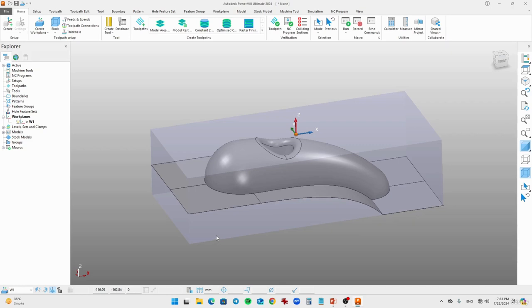In this model area clearance, we are going to apply the roughing operations, all the roughing operations, to give a certain shape to the block. In such operations, you will get a rough idea of how your workpiece looks. For this operation, you just need a tool. You can apply patterns and boundaries on this side using the model area clearance. So let's do the toolpath.